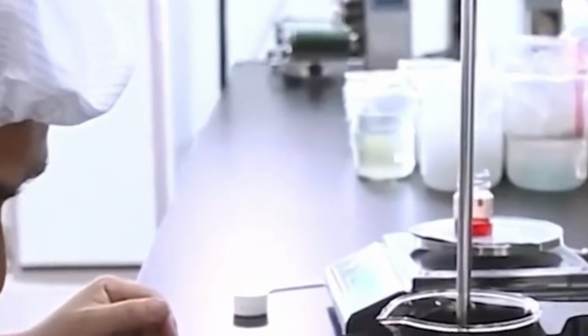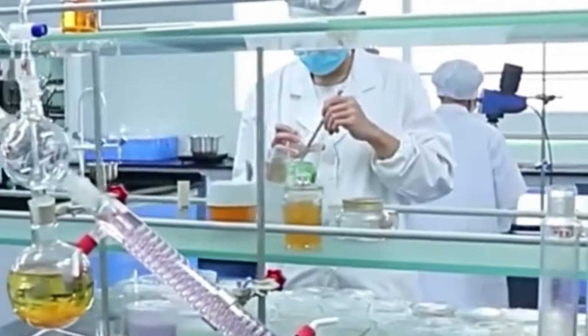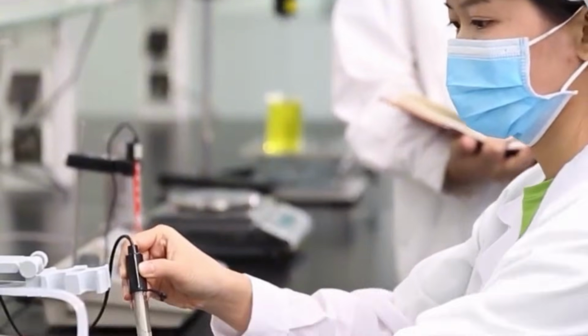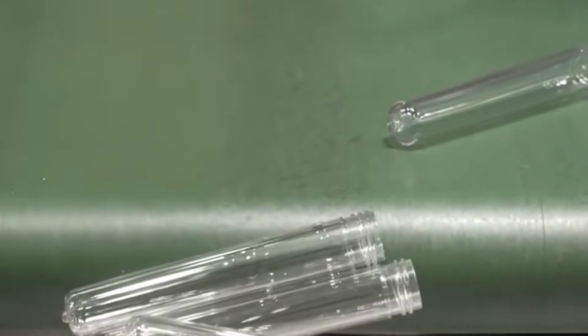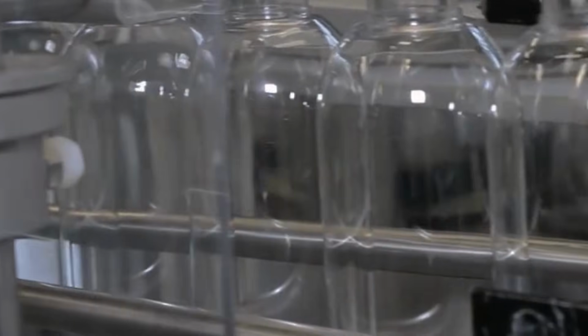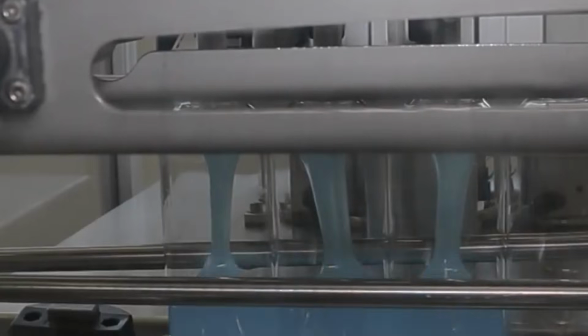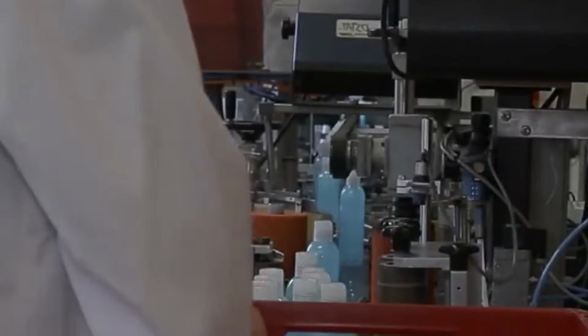For formulations using solid or paste surfactants, the materials are pre-dissolved in auxiliary tanks. These tanks are heated via steam or hot water jackets to reduce viscosity and accelerate dissolution. High shear mixers are used to break down surfactant agglomerates before the solution is transferred into the main batch vessel.